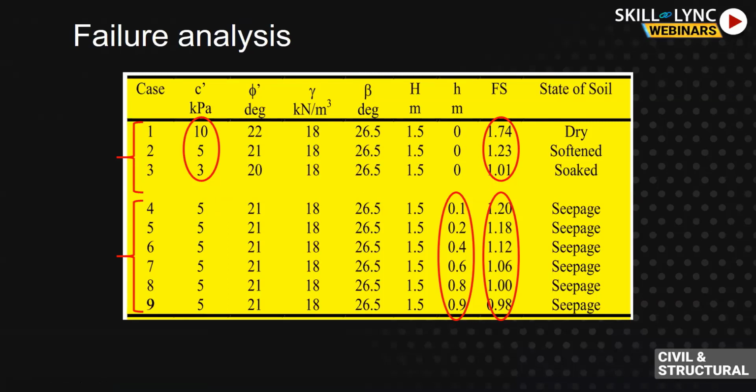The soil would have lost the cohesion. And just to brief upon, cohesion is generally contributed by all soils. It's contributed by the cementation effect in soil. This particular soil formation, residual soil formation, has no cementation effect. If there's no cementation, it loses its cohesion completely. Then also, the cohesion is contributed by, when the ground is unloaded, the ground becomes over consolidated, so it becomes high in cohesion. So that's the first possibility: the cohesion dropped, safety factor dropped.